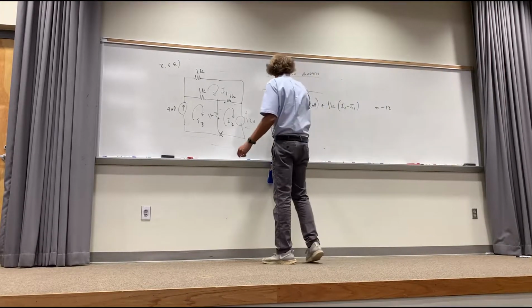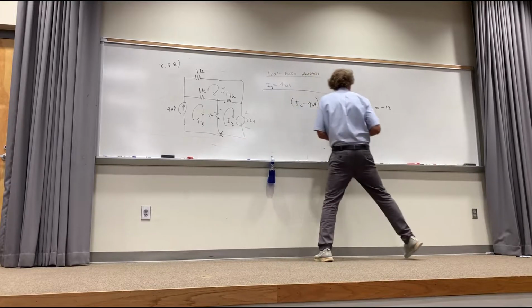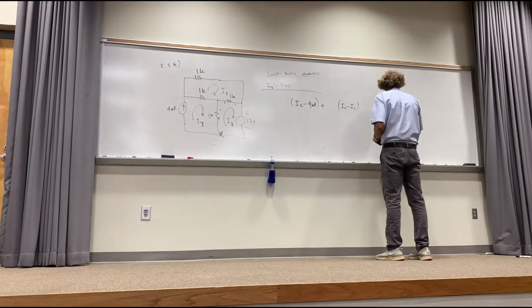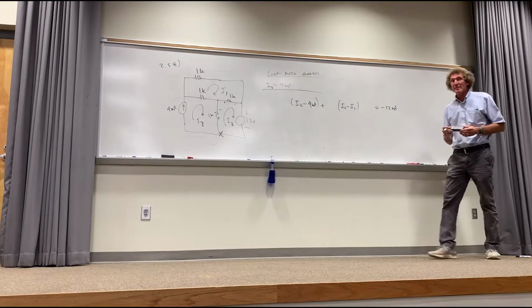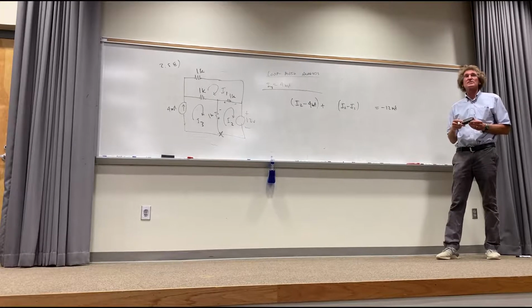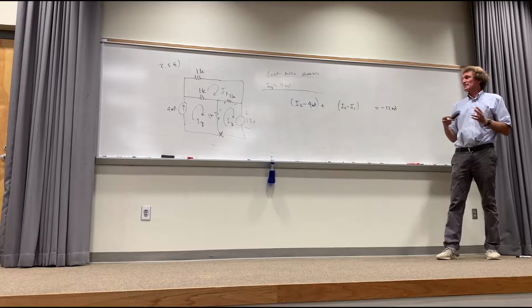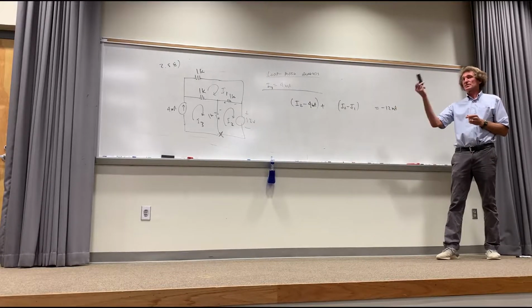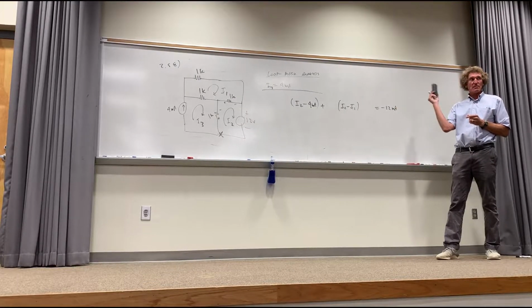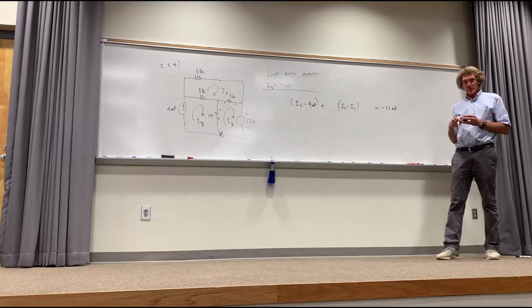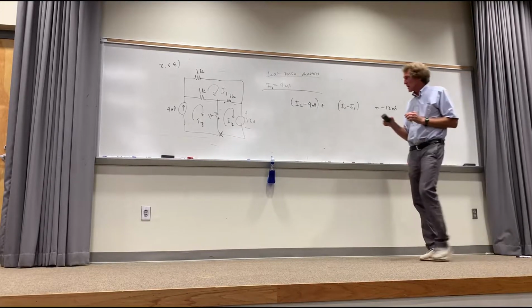I'm gonna divide by K. Now this makes this 12 milliamps, right? 1 over 1,000 is milli, correct, class? Now after that, I'm gonna take the minus 4 milliamps to this side too. See that minus 4? That means I'm gonna add 4 to this, right? And that means this will be minus 8 when I'm done, correct, class? So I'll just do that.